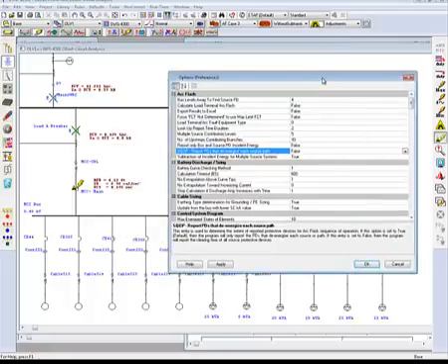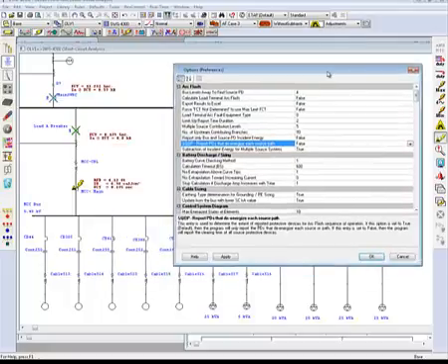Currently I have it set to false, and as shown on the one-line diagram, when it's set to false, it first shows you the first device to operate. For this case, this is a radial system, so then it's going to show you the next line of defense or the next operation of devices following first operation of your device.